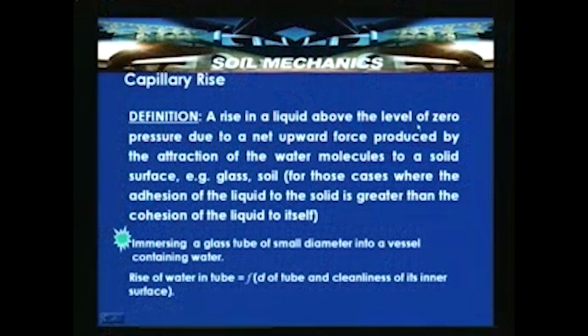So, capillary rise is a rise in a liquid above the level of zero pressure due to a net upward force produced by the attraction of the water molecules to a solid surface, for example glass and soil. This occurs in those cases where the adhesion of the liquid to the solid is greater than the cohesion of the liquid to itself. This can be demonstrated by immersing a glass tube of small diameter into a vessel containing water. We will consider this and then try to derive the theory behind capillary rise.